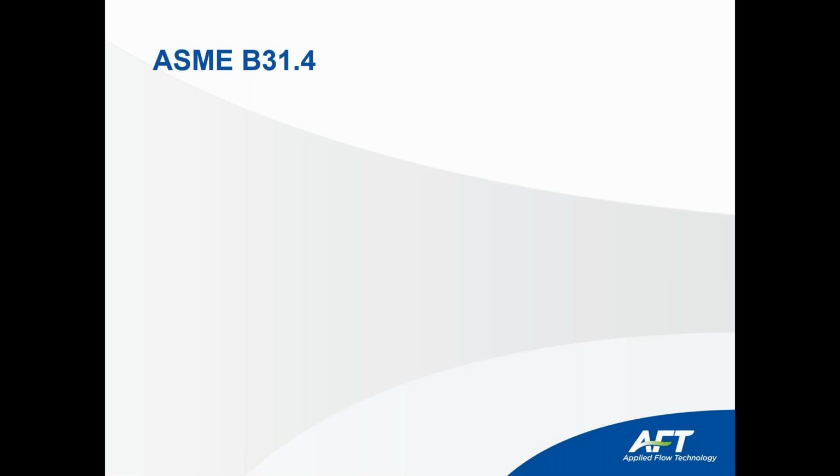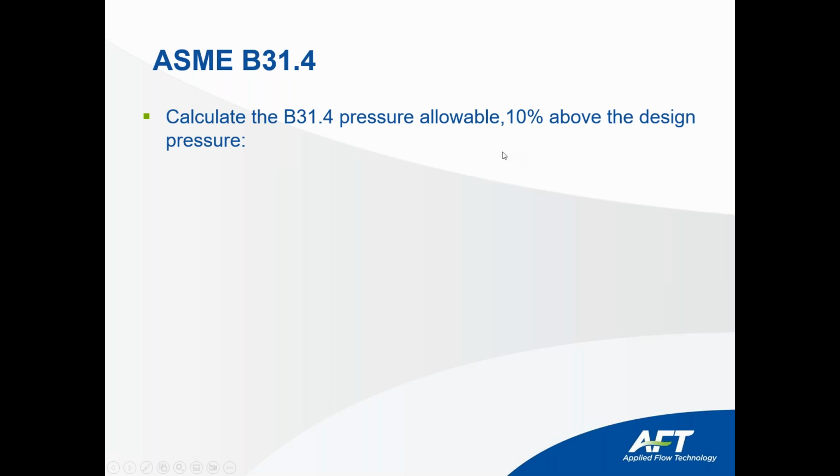So let's imagine we're working with B31.4 and AFT Impulse. If you're working with B31.4, you first have to calculate the allowable pressure by the code, which is 10% above the design pressure. For this example, it would be 385 psig. Once you establish that, you set the design alerts to detect this value, making sure it's not violated during the transient event.